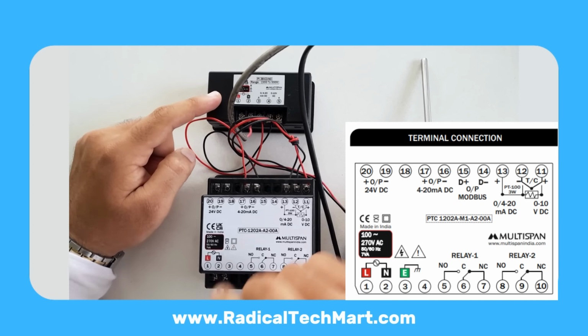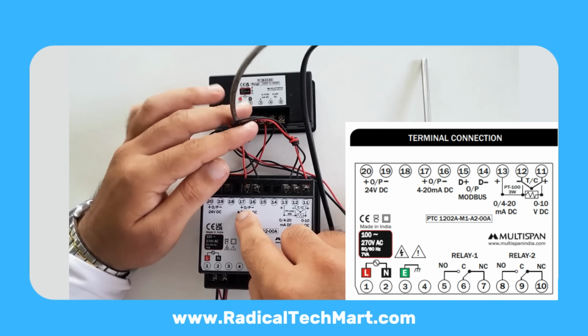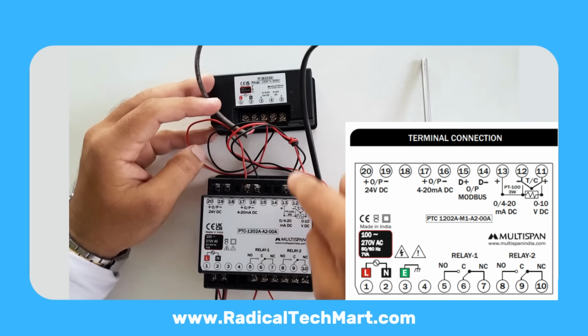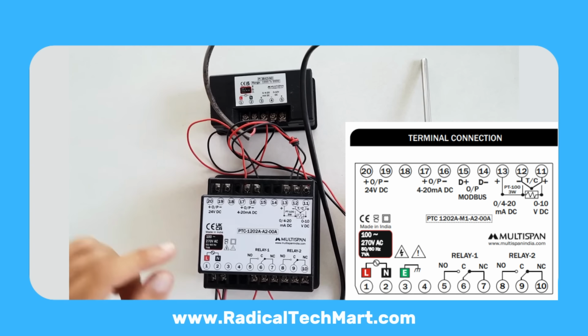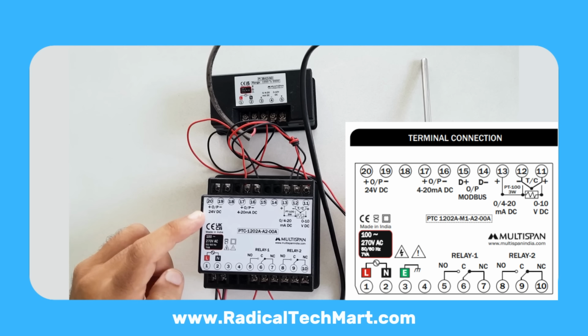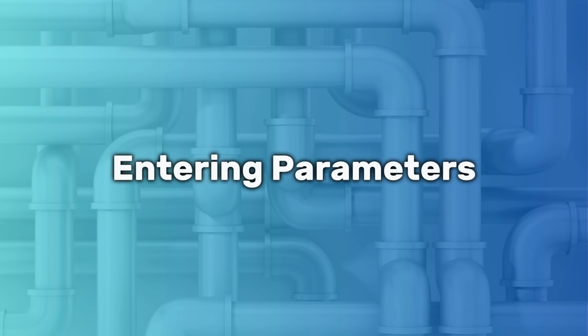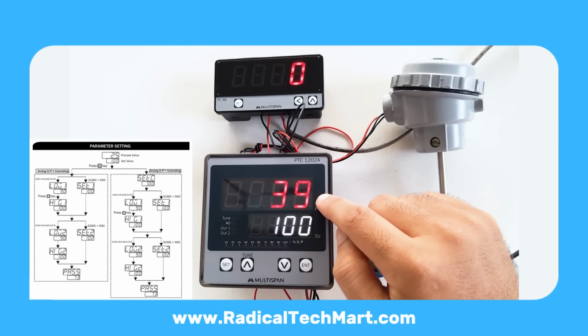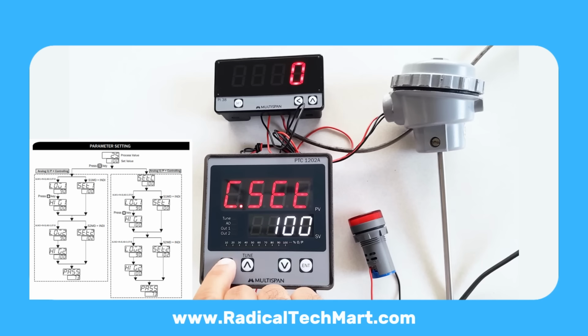Analog output, 4 to 20 mA, to a remote indicator, example Pi38: controller I/O plus to Pi38 plus, controller I/O minus to Pi38 minus. Loop power: use terminals 19 to 20 to feed 24 volts DC to your transmitter, up to about 30 mA. No separate SMPS needed. Power on both the controller and the indicator. On boot, you'll see input type on the display, example J-type, and the analog output mode, example control.